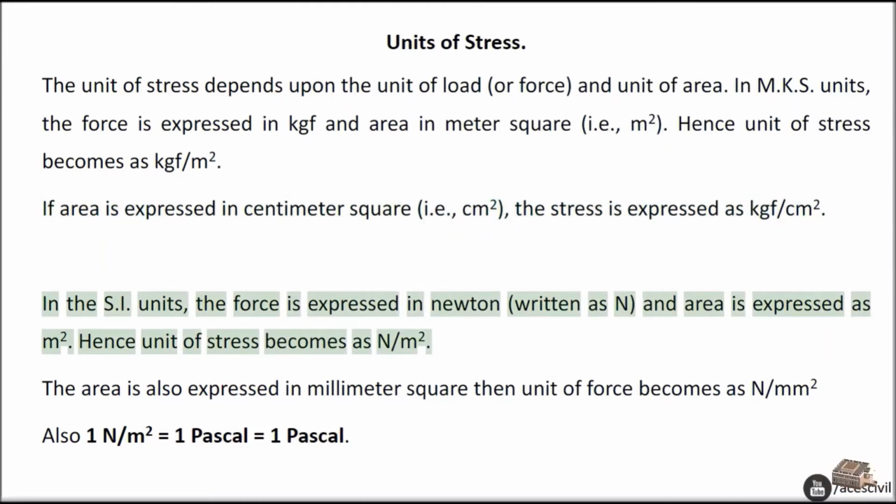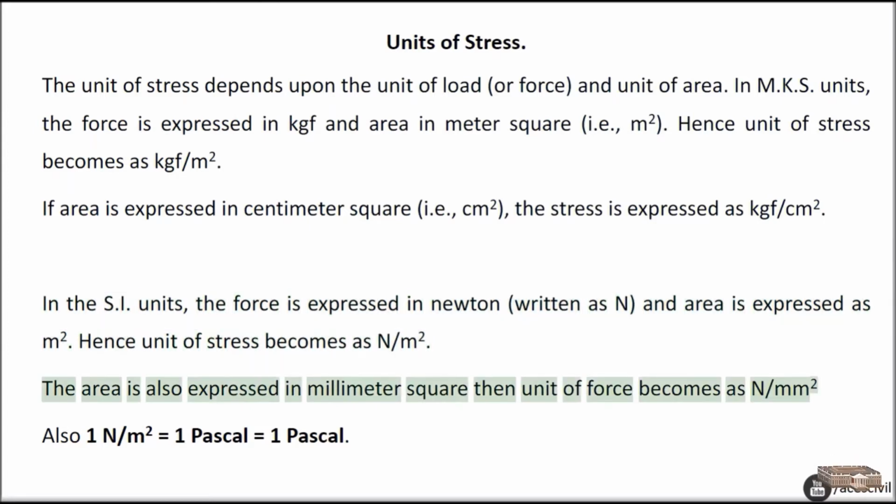In the SI units, the force is expressed in Newton, written as N, and area is expressed as m². Hence the unit of stress becomes N/m². If the area is also expressed in millimeters square, then the unit becomes N/mm². Also 1 N/m² equals 1 Pascal.